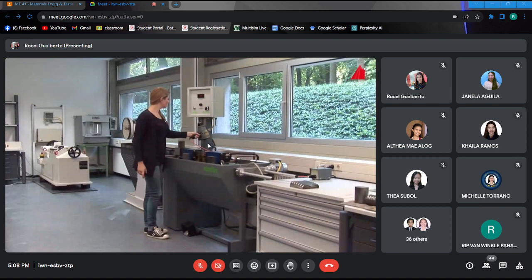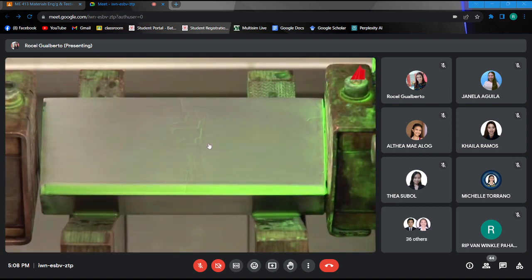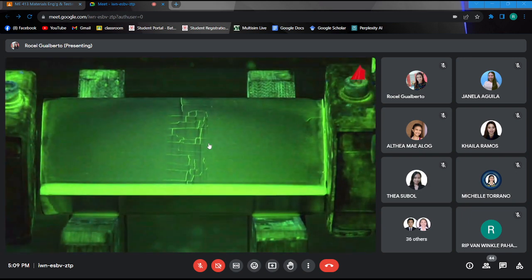The lines can be seen much better under ultraviolet light, and particularly well at darkening the daylight. The suspension contains pigments that cover the magnetic particles and fluoresce under ultraviolet light. The particles run off in areas free from defects, and they are attracted and clustered near defects. This workpiece shows a whole array of cracks.